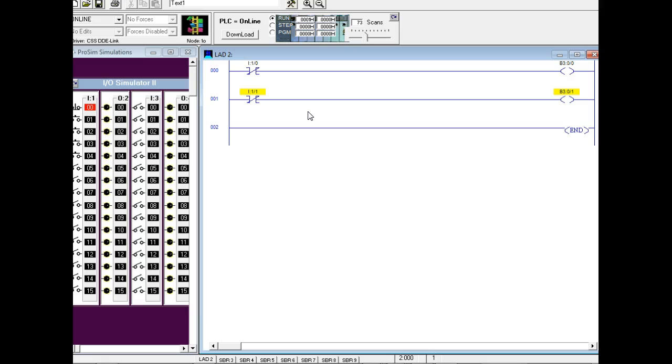But I screwed up on the top one because I'm an electrician. I think, by George, I've got to have a normally closed contact for a stop button. So we're using our normally closed contact out there. You do in motor controls, but not in PLCs, because in PLCs what you're changing is what it sees as true and what it sees as false.